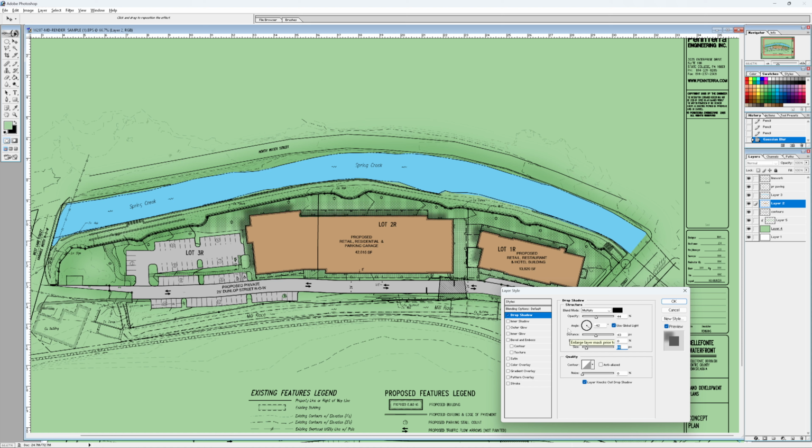And this is where having your buildings and your pavement and everything like that separate matters, because right now, let me change this. All I did there was change the direction of the sun, and that moves the shadow. Now you'll see the shadow is being blocked by the pavement. That's not how it would work. So the pavement has to go below the building layer. And as soon as you do that, now the shadow goes out over top of the pavement, which would be more realistic.